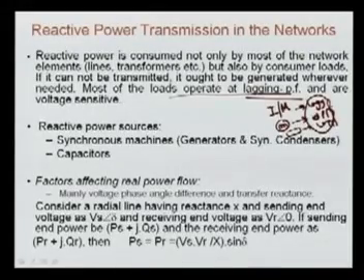So, if reactive power cannot be transmitted, it ought to be generated wherever it is needed. Also, this reactive power or voltage problem is a local phenomenon. It is not possible to transmit reactive power from a very far end to the load center. However, for real power it is possible.